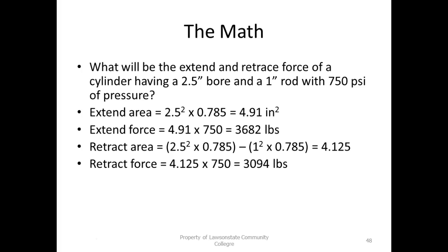So, here. What did they do here? When they calculated the pressure using 750 psi, they came up with 3,682 pounds of extend and 3,094 pounds of retract. So you've got to size for both.